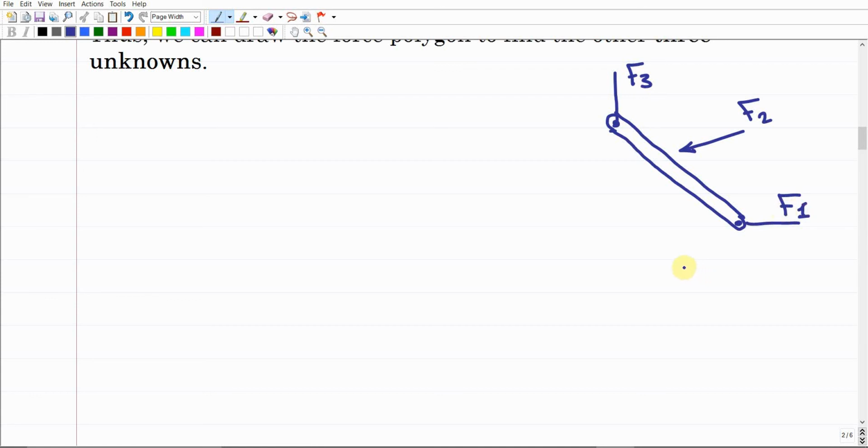You're going to observe something here as I'm presenting these three forces: I'm putting the arrow direction on this force. What does it mean? It means that I'm pretty sure of the direction of this force, and I even have its magnitude. Remember that any force is a vector quantity that requires magnitude and direction. So let us assume that the magnitude of this force is 40 Newton. This is the magnitude, and this is the direction of the force. Since I'm putting an arrow, it means I'm pretty sure this is the correct direction. It is directed this way.